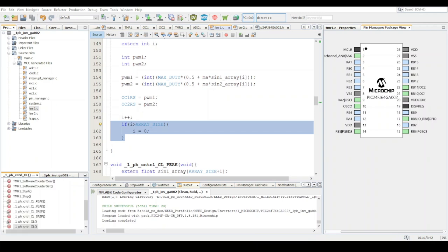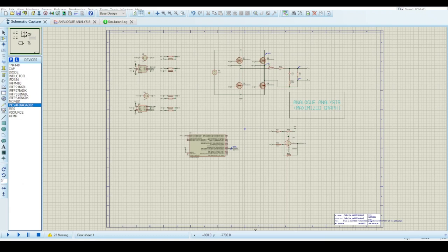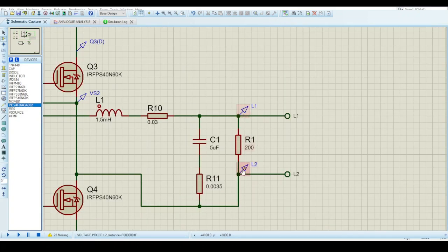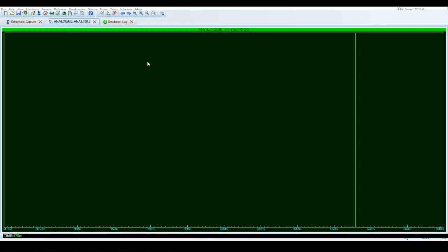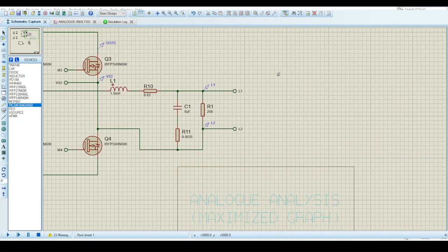All right, just to make sure I got it right, I've set up the MA to be 0.65. I guess I could just reduce that to check. All right, I can change over now to a different view. Let's zoom in. So tagged 2, L1 and L2. I can go there, edit graph. Let's change that time to 300. Actually, just make it so it goes quicker, 250. So we'll add traces, probe L1, L2, and we're going to say L1 minus L2. We'll name that L1.